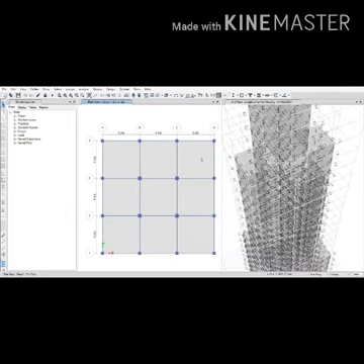And finally, after assigning loads and shear loads from the assign option, and after calculating the values for the wind loads from the code book and assigning them, finally we are required to analyze this.